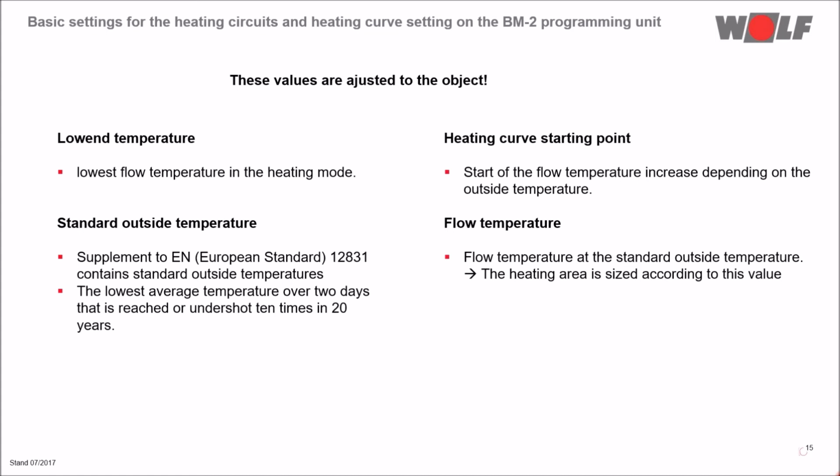This is the lowest flow temperature in heating mode. Then there is the heating curve starting point. This is the point at which the flow temperature is increased slowly depending on the outside temperature. The standard outside temperature is defined in a European standard.